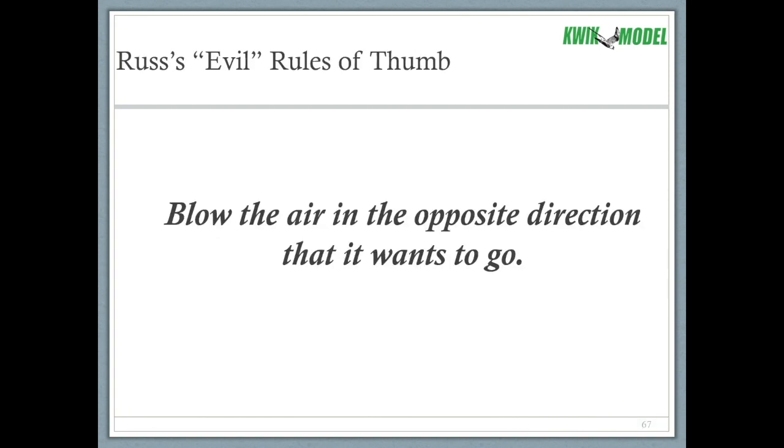Okay, so one of the most controversial topics that I run into in residential HVAC design, the topic that people get the most riled up about, is where do you put a register in a room? Should it go back interior to the room, blowing across the room, or should you put it out over the window? Or like out in Las Vegas, they insist on putting registers dead center in the room. A lot of people over the years have put registers out over the windows, and a lot of people now start to insist on putting them more interior to the room, blowing out across the room.